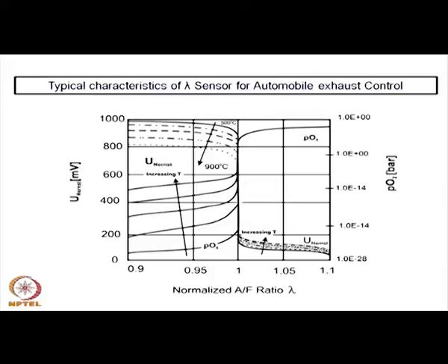However, if the carbon monoxide concentration is very high, then the catalyst life goes down, and therefore, one needs to control the carbon monoxide concentration in the exhaust gas which goes into the catalytic converter. So, these two devices, the sensing device and the catalytic converter, have to work in tandem, so that the combustion efficiency is high and the environmental problems are eliminated.